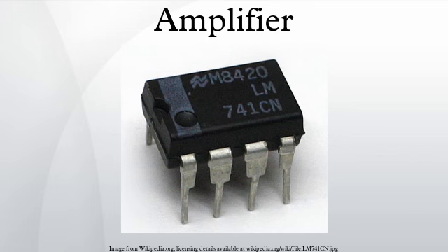Amplifier circuit. The practical amplifier circuit to the right could be the basis for a moderate power audio amplifier. It features a typical design as found in modern amplifiers, with a Class AB push-pull output stage, and uses some overall negative feedback. Bipolar transistors are shown, but this design would also be realizable with FETs or valves. The input signal is coupled through capacitor C1 to the base of transistor Q1. The capacitor allows the AC signal to pass, but blocks the DC bias voltage established by resistors R1 and R2 so that any preceding circuit is not affected by it.